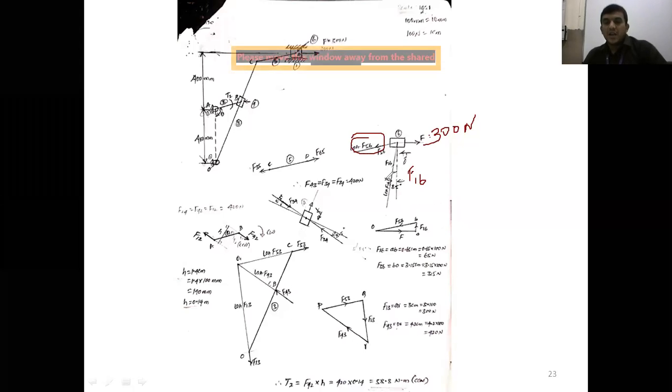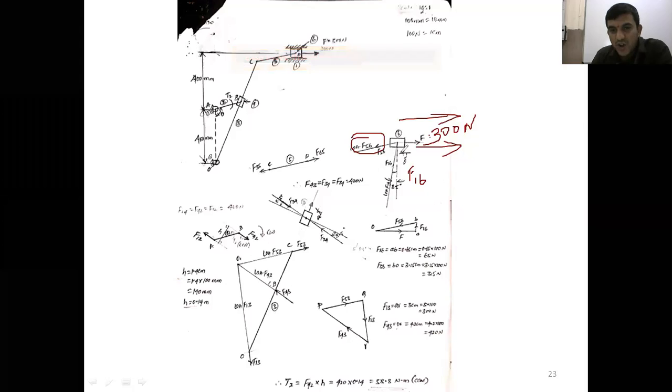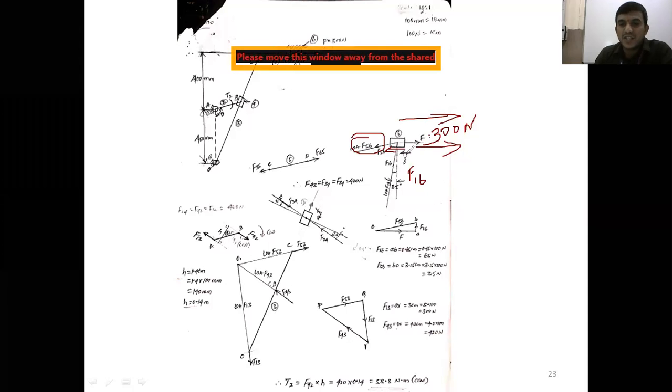Right? Again, here the mu value is given. That is very important. When the mu value is given, we have to consider friction at the joints or the sliding pair here. The mu value is given only for the sliding pair. Now the force F is acting here, away from the slider in this direction. When the force is acting here, the slider also moves in this direction only, right? At the same time, at the joint between link number 1 and link 6, the surface will resist the motion of the slider in opposition to the applied force. That is the friction force.